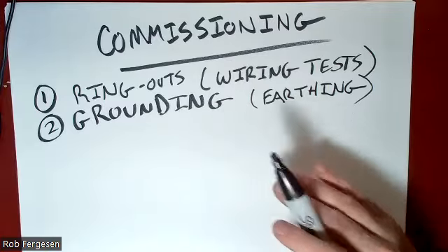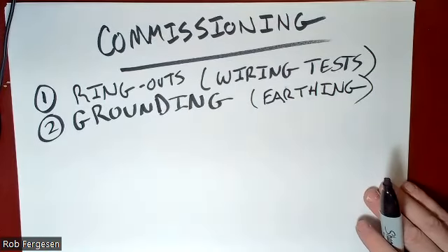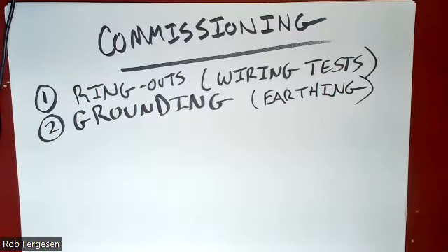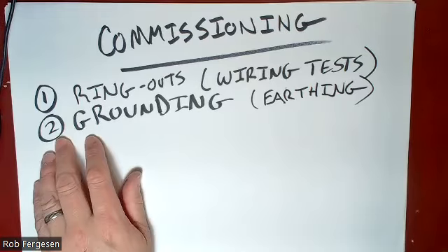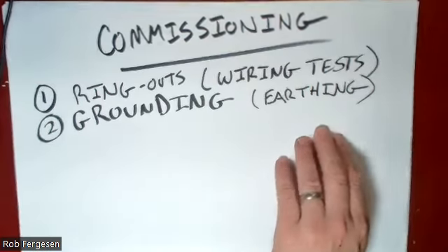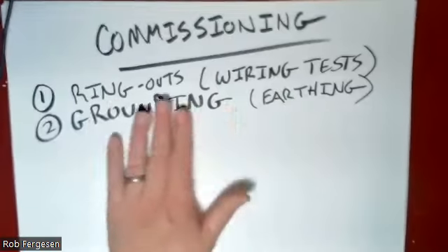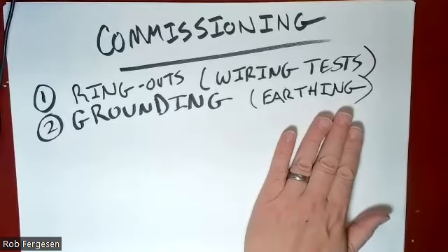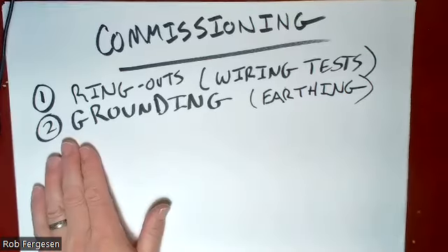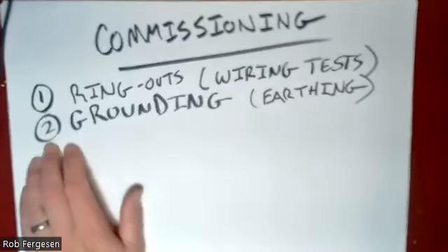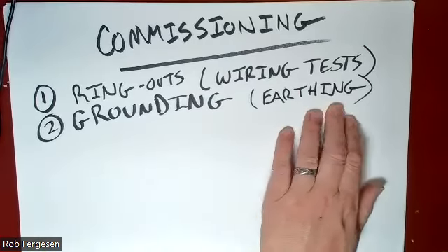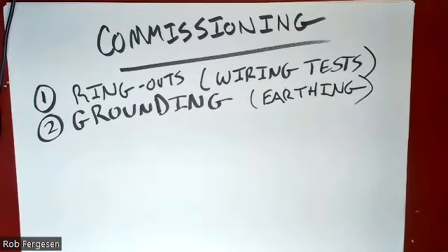And I can't tell you how many times I've seen that screwed up. And with grounding, you're going to verify not only that you see a green wire hooked up to a ground wire that goes to your building ground, but you're also going to test it with a multimeter and make sure that you don't have any floating grounds and everything is grounded out to the same level everywhere if they have any physical interactions. Once again, in the world of Ethernet or Wi-Fi connected devices, grounding is a little bit less of an issue, but we still want to do that very, very carefully.